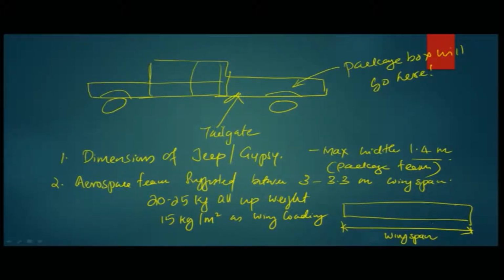We are not talking about an aerofoil. You can think about this as the chord, or the distance. So, we multiply, and this total area should come up in such a way that if you assume 15 kg per meter square, this total area should be able to lift a total weight of about 22 kgs. Once this was finalized, the wingspan was set to 3.3 meters.